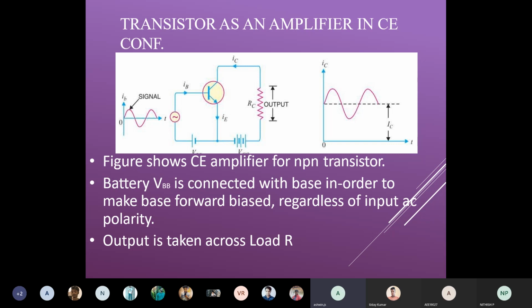Actually here I am giving two biasings. One is base biasing, another is collector biasing. For collector biasing, much more, 12 volt I will give. Base is based upon your input signal, which I will give in terms of 1 millivolt, 2 millivolt. But your collector voltage is 12 volt. Suppose the transistor is in on condition, at that time your output voltage is 0 and current is maximum. If the transistor is in off condition, the voltage is higher and current is 0. So based upon that, the amplification will happen.